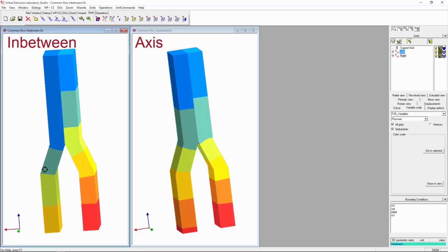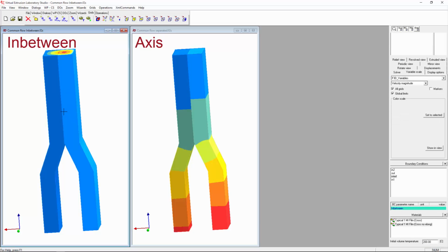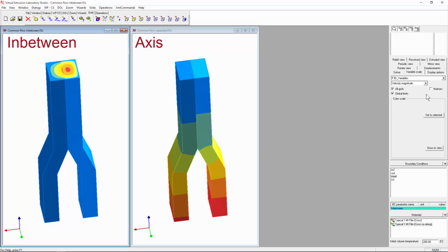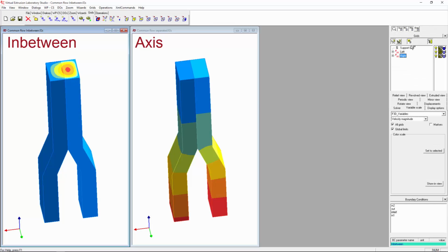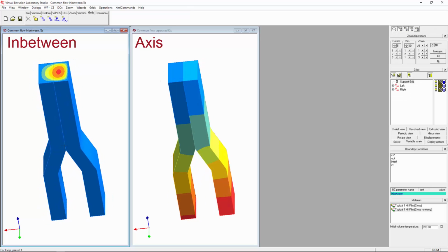We only allow the polymer to slide on that boundary, similarly as we did with the axis, but now when the sliding from left and right are sort of being synchronized, so this is very close to reality. You see the velocity profile is very much as we would expect it probably, but the center should be in the middle, of course, right?